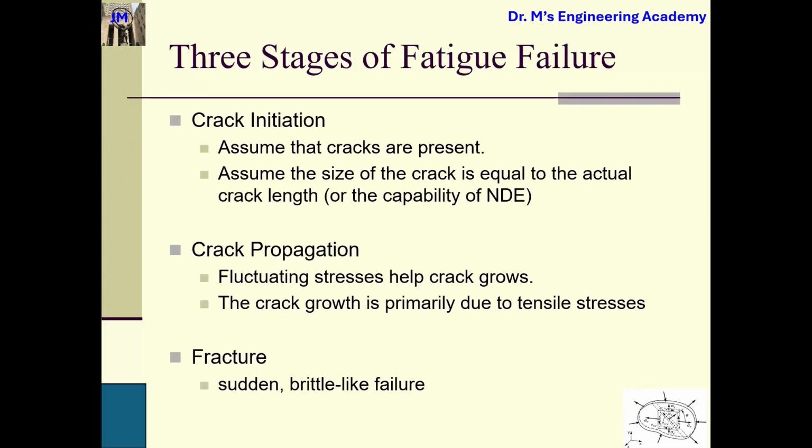These are three stages of fatigue failure. Whenever you have a specimen, no matter how well you have manufactured it and how smooth you claim the surface is, we still have some cracks on the surface. So the first stage is crack initiation, and we just assume the cracks are present.